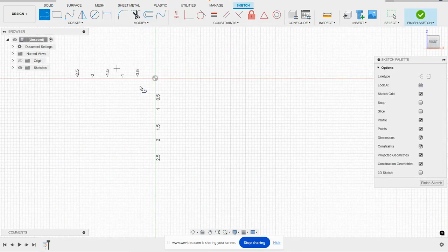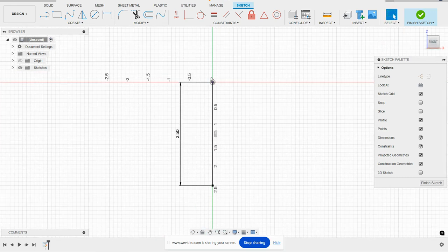And I'm just going to draw a line from the origin down. We're going to keep this totally vertical. I'm just going to bring this down like 2.5 inches. The top part of my necklace, my pendant, is going to be up here about where the origin is, and I'm just giving myself a line as a reference here, because we probably don't want a pendant to be much longer than 2.5 inches. And even at that point, it's still pretty large. So I'm just going to give myself that line as a reference right now.